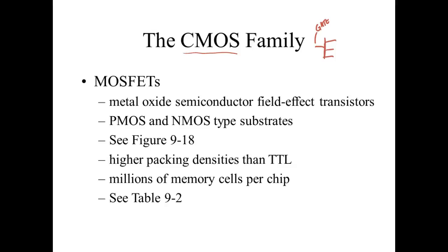And you could damage it just by doing what? Just by handling it. So this is why when you go out and buy a new motherboard, if you're into building computers, it's going to be in an anti-static bag. All your memory is going to be in special packages. And then we have special considerations. This right here is called a static armband. That's all it is right there.